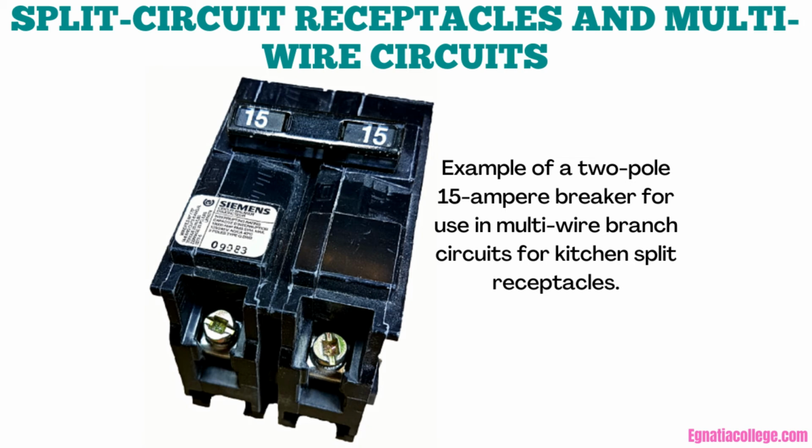Therefore, when the breaker in a panel supplying a receptacle is turned off, current cannot be flowing in the neutral conductor. Still, Rule 4-0221d requires that any identified conductor can be disconnected without disconnecting any other identified conductor. The hazards of open neutrals are covered in Unit 19. When multi-wire branch circuits supply more than one receptacle on the same yoke, a means must be provided to simultaneously disconnect all of the hot conductors at the panel board where the branch circuit originates.